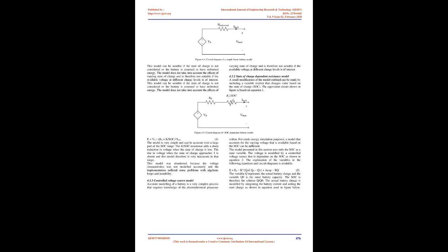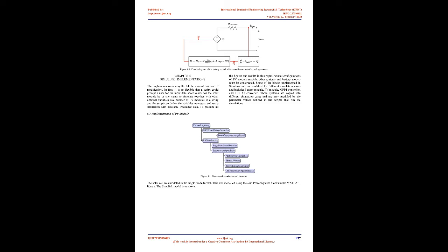These systems are connected to a broader electricity network. The PV system is connected to the utility grid using a high-quality inverter, which converts DC power from the solar array into AC power that conforms to the grid's electrical requirements. During the day, the solar electricity generated by the system is either used immediately or sold to electricity supply companies. In the evening, when the system is unable to supply immediate power, electricity can be bought back from the network. Figure 2.11: Grid-connected PV system.